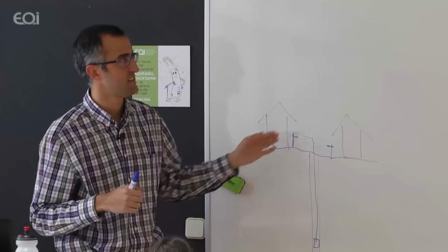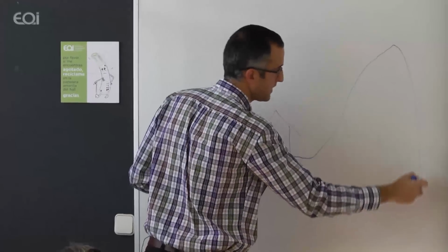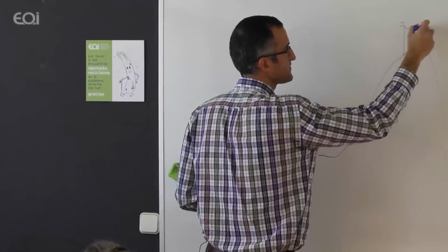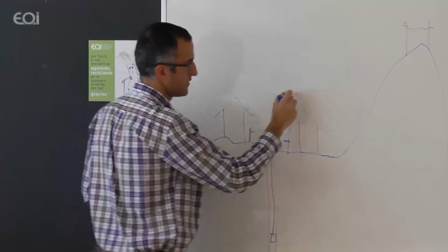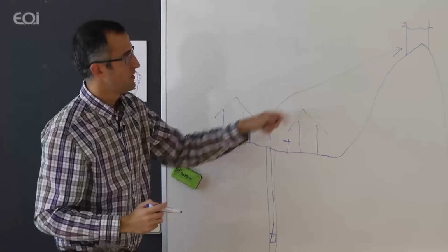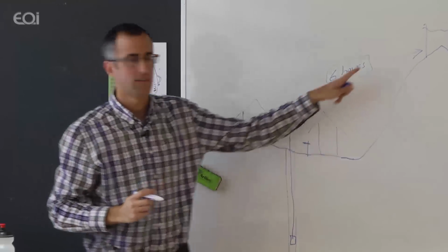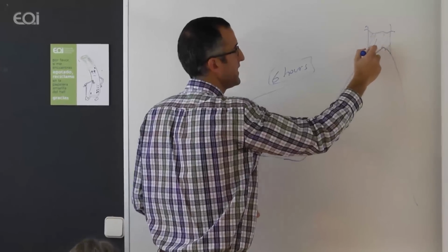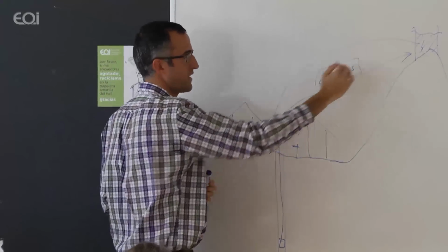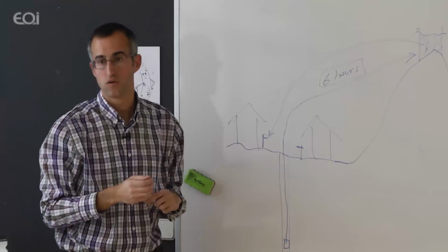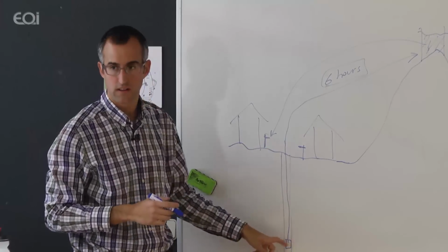So the best option, and it is a mixed water supply system, is to do what we did here. We have a mountain here, so we install a tank here. We took the water from this borehole with the pump for 6 hours, for example, during the night. We were pumping the water from the borehole and filling the tank, and then there was another pipe to the fountains that were pressurized. The tank was pressurizing all the fountains during the day. So if you want to have water during the day, you will not have to be working the whole time with the pump.